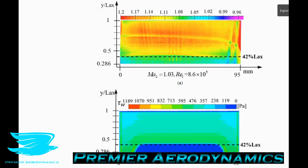So we can say that the CFD is quite well validated. Not only does it predict the Mach number distribution over the airfoil, but it also predicts the boundary layer transition much more accurately than I even expected, based on potential difficulties of this CFD and differences in the CFD setup. So it is still quite well validated. It's giving quite good results. So that means that TSP, or temperature-sensitive paint, can quite accurately tell us where the transition point is along an